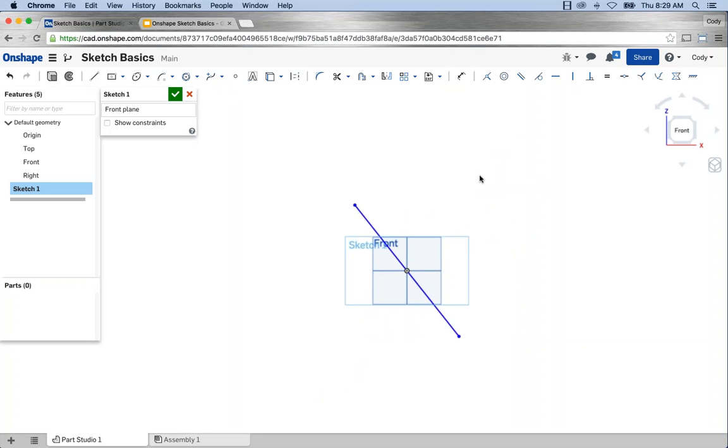That's often where points are very valuable. You need to attach them as to then go in and maybe dimension or constrain the geometry that you're trying to sketch. So points, I like to think of them as construction. They just allow you to attach things as references and use them as dimension points or constraint points. So that is a simple point. Again, you can use it in a number of different examples.